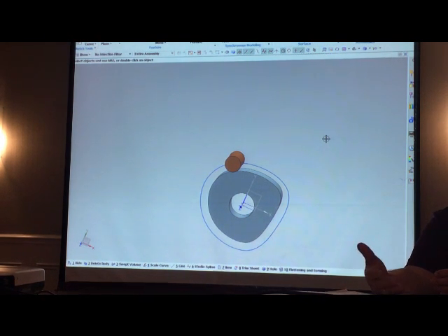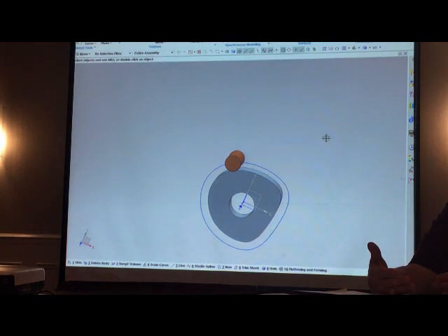But if I then did a STEP file, or I did mass properties, or an IGES file, or there are certain companies that have rules. They run Checkmate. There's a test in Checkmate that says, do you have more than one solid body in your model? And it'll scream at you if you have more than one solid body.